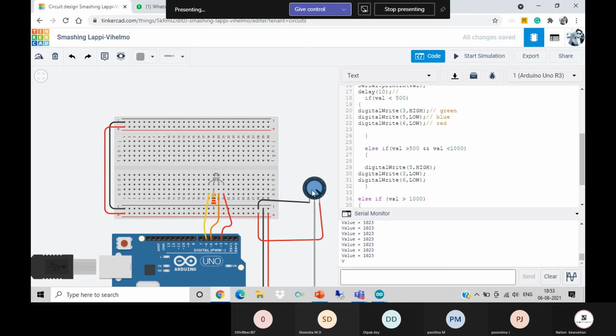This sensor will help us detect that value when the minimum threshold for the moisture is touched. If it is touched or if it is below that, then we are going to turn the pumps on automatically. Fine. So this is how some simple things work in an embedded system. And if we are putting that data to remote servers, remote databases, or to the user, and also providing a user interface to tell the user that it is below that point and they can turn on the pumps, this is what IoT is. If it is able to be turned on from anywhere around the world.